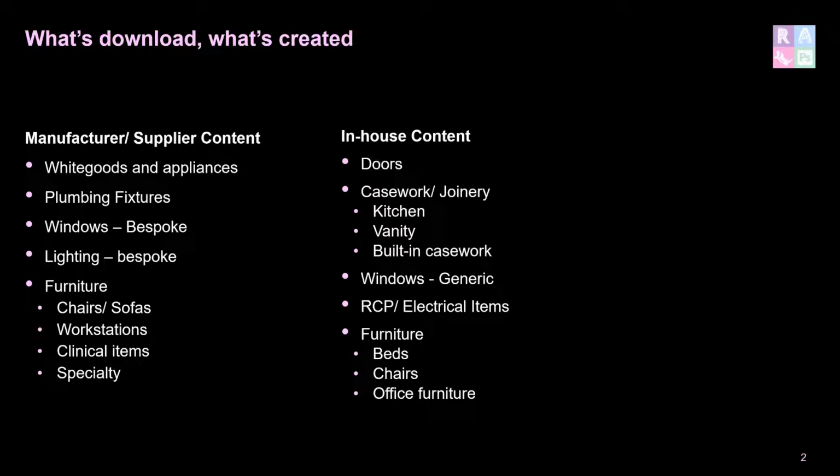You don't really just download them online. They just appear the way you want. They could be different sizes. They could be the wrong symbols. They could be presenting wrong. They may not show in certain views. They may have different line colors. So generally, you want your RCPs to read the same from project to project. So it's worth the time investing to create those items yourself and then just take them from project to project.